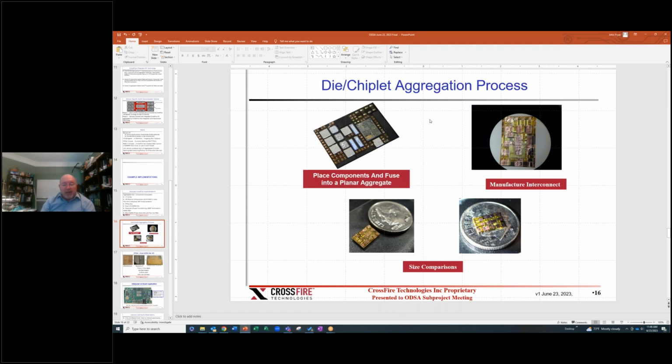And so you have to go through and calculate that for every, basically you're doing a new mask for every device on the wafer. And then they use some e-beam type of lithography techniques to actually make those connections. Now that has some limitations as far as how much area you can correct, because if you're trying to correct too much, you start having angles where the traces will start overlapping one another. So I think right now, someone may have a better number than I do, but I think in production they're at around 10 to 20 micron.